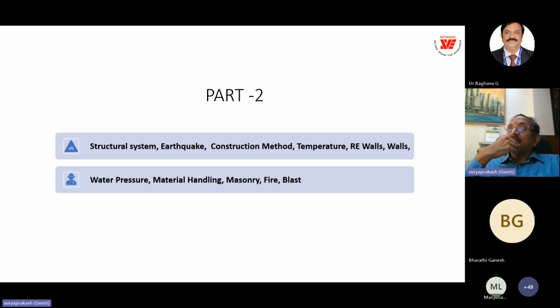So once it happened in one project, about 36 cubic meters of concrete did not set. When we investigated, we found that the amount of retarder given was correct, but you have to give the dosage of retarder every hour, actually, one dose every hour.